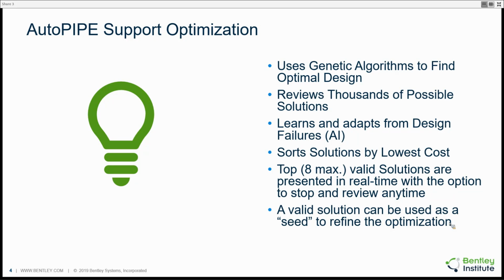For a given pipe stress analysis problem, the support optimizer feature automatically considers thousands of solution configurations and weeds out the invalid trials that do not satisfy the specified design criteria. This design criteria is taken from a stress model. In addition, support groups and locators are set by the user. From the results, the user can easily review and compare many different solutions in real time as they are produced, and ultimately select the best and most cost-effective design.